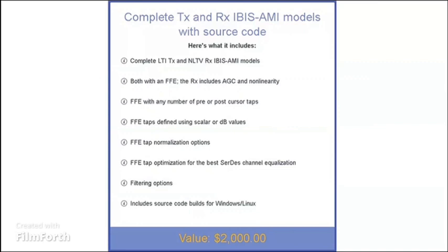The FFE is usable with any number of pre and post cursor taps. The taps can be defined using scalar or dB values. The taps have different normalization options and will automatically optimize themselves for the best SerDes channel equalization. It includes filtering options and includes source code builds for Windows and Linux. Its standalone value is $2,000.